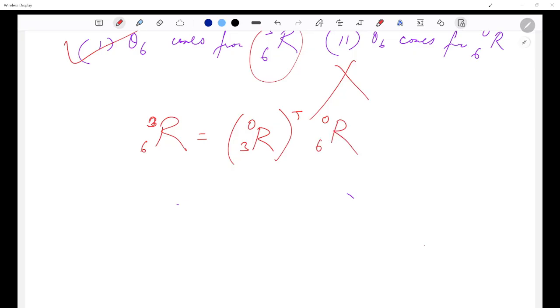And that way we can write this, because the end effector with respect to the base frame is basically a multiplication of two rotation matrices. So if they are decoupled, then we can write R 0 to 6 as the third link with respect to base into the sixth link with respect to 3, right? That term would have been here, and then we brought it here by taking the inverse, and it can be written as the transpose.